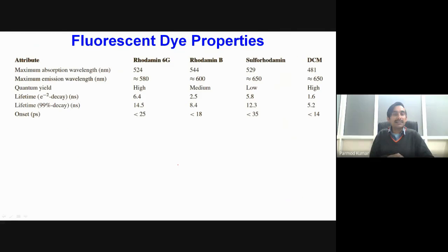Sometimes, because particularly we have to acquire the light signal from the particles once we have incident some laser light on them, due to the scattering effect, we coat the particles with some fluorescent dyes in order to improve their output signal capacity. So these are the different types of fluorescent dyes which are normally employed to coat the particles, and these are their corresponding optical characteristics.